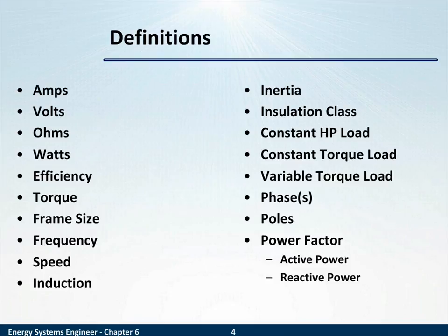The phase of a motor is the number of individual voltages being applied. A single phase motor has one voltage in the shape of a sine wave, alternating current, applied to it. A three-phase motor has 3 voltages applied to it, and if you consider that sine wave, as we will, breaking that 360-degree cycle up, a three-phase motor would have three phases that are 120 degrees off with respect to each other, so that the peaks of voltage occur over time intervals and balance each other out, balancing the power received and delivered.